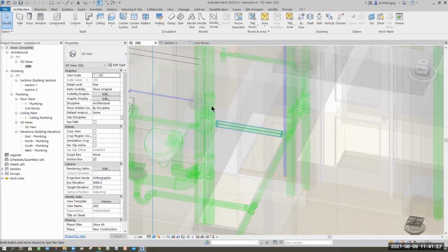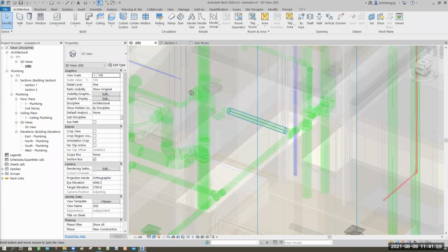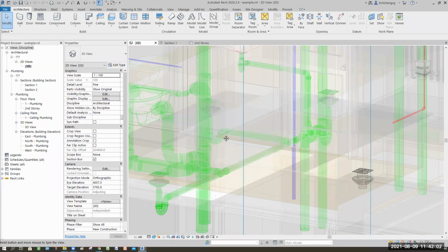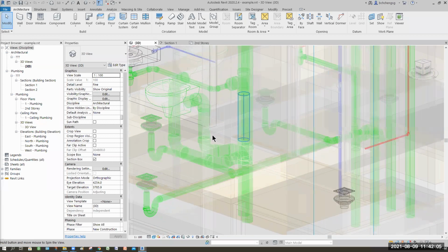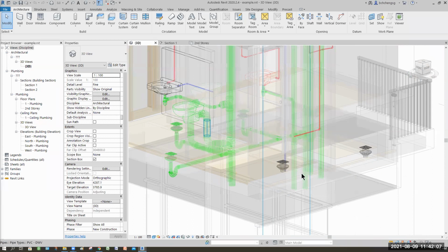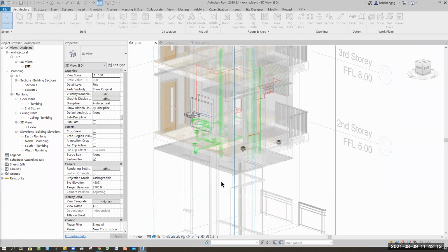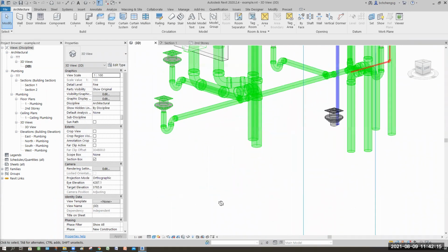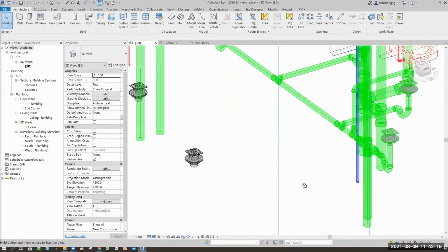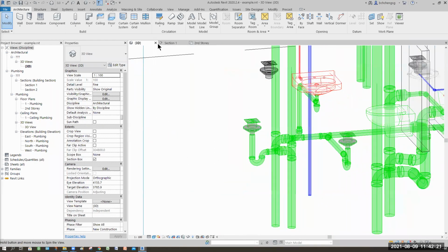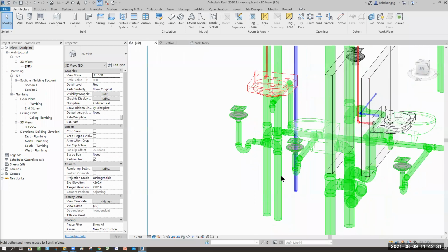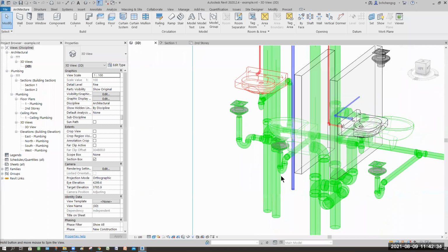All right, so somehow or rather, a lot of details are not added yet. Just the main piping that you do, how you design that. Sometimes you may temporarily want to hide this Revit link, uncheck it. So this is how it looks like. From time to time you may have one 3D view with the building together, then one 3D view just the plumbing, or they call it sanitary, so that you can design. So you tell me, one screen enough? No, 2 screens.